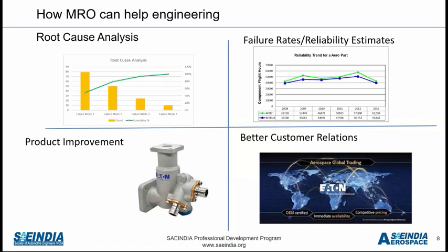You might have heard in the aerospace business that most of the industry stakeholders, whether it is OEM or operators, talk in terms of reliability, that they want a very good high MTBF, or MTBUR. So MRO businesses help in doing this failure rate estimation, because when you are in a design and development phase, you will use a handbook data approach or some legacy information to come up with an estimation of the reliability.